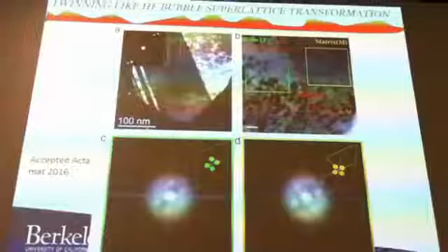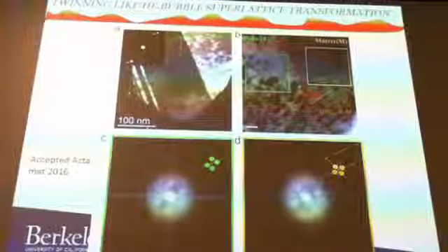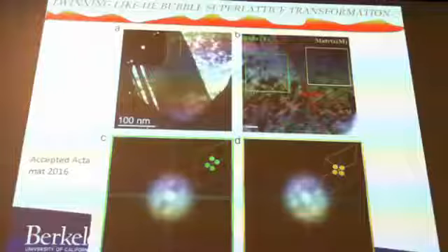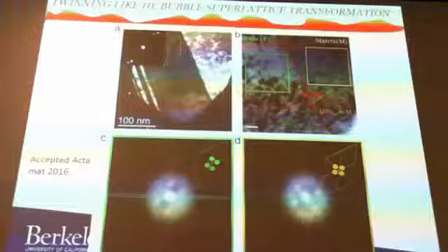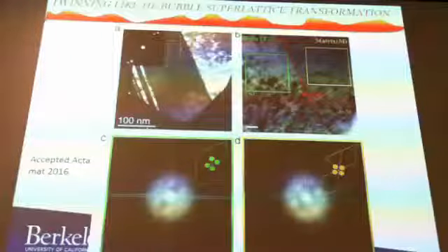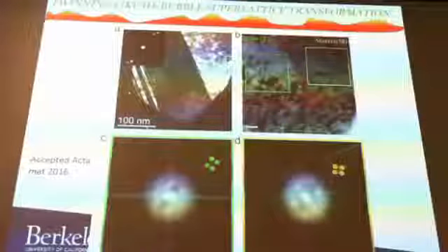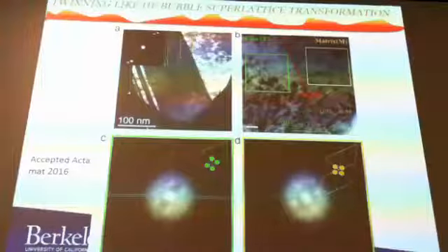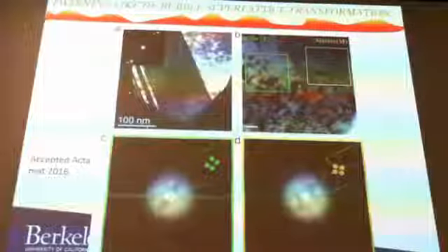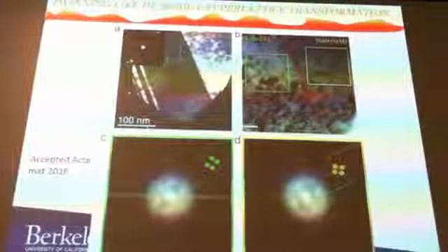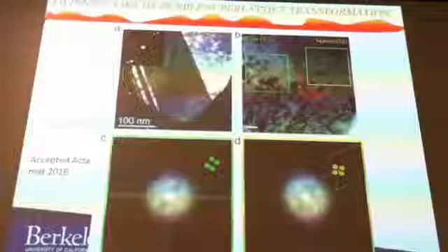And most exciting to me is the fact that if you have this type of twin structure, which is a folded lattice, then you can also see that the helium bubble superlattice rotated with this twin. So this twin causes a 60-degree rotation of the host copper lattice, but it also rotated our helium bubbles. The question is, how do these nanoscale helium bubbles flip over? How did they suddenly just flip and change their orientation? How does this happen?